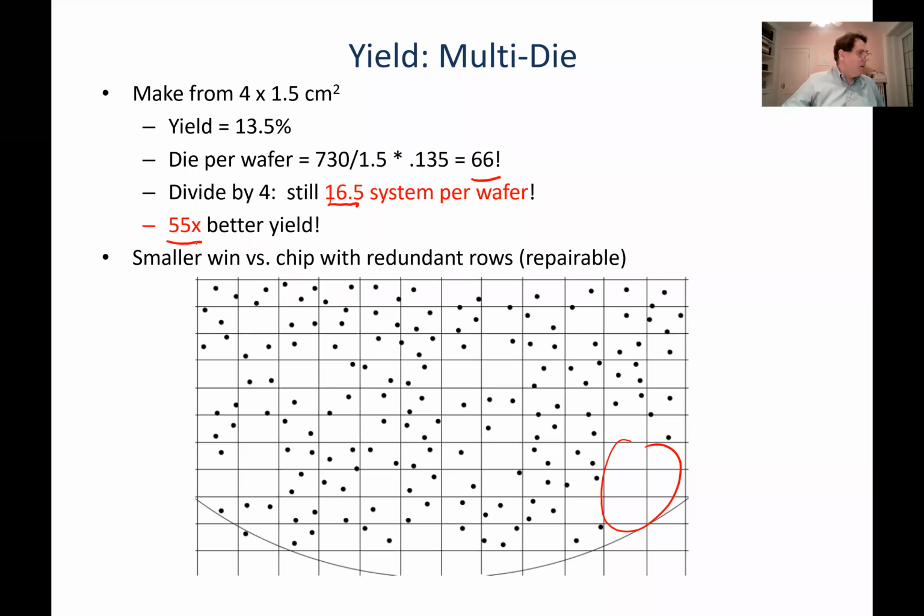Intel has not embraced this technology as aggressively, which is interesting. And probably one of the reasons is, remember I mentioned, I think last lecture, that Intel's FPGAs are repairable. They build a small number of extra rows. So if they sell you a chip that has 100 rows of logic, it really has somewhere around, say, 104 rows, which means that as long as there's no more than one broken row in a region of 25 rows, they can repair it. They'll skip the broken row, and they'll program some fuses to tell the programming hardware that it has to skip that row. So Intel would not get the same yield improvement because they've already captured some of this yield improvement by making their chips repairable. So that's a different technique, which is also interesting.